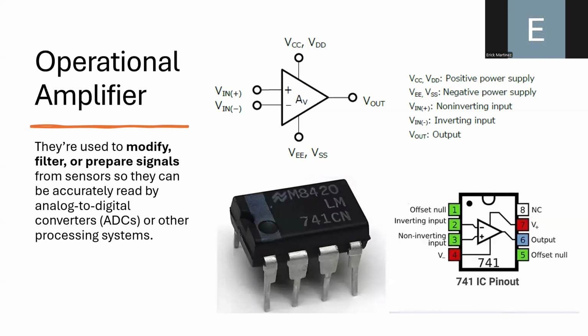This is the picture of the operational amplifier. It's basically a chip. There are many presentations. This is a relatively small presentation of an operational amplifier, and it is one of the most commonly used in many audio amplifiers, for example. You can use this type of device. And this is the connection diagram that basically relates these pins or legs of the chip with the diagram that we saw in this part. Some of these pins are associated with the positive and negative terminals, other ones are associated with the power supply, and all other ones are not connected. So this is basically the connection diagram of this chip.